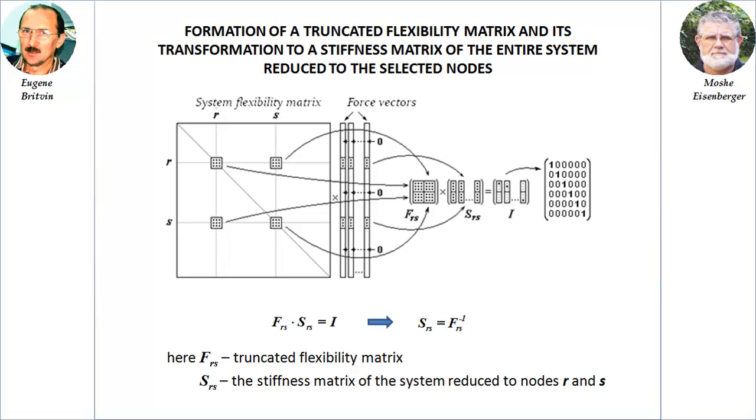But here, everything is hampered by the flexibility matrix of the entire system F itself. First, the system's flexibility matrix is completely filled, which causes problems with storing the matrix. Second, even taking into account the symmetry of the flexibility matrix, the cost of generating it for our computational schemes may be incommensurate with the capabilities of modern consumer computers. Nevertheless, the specifics of the task at hand make it possible to solve this problem with very little computational effort.